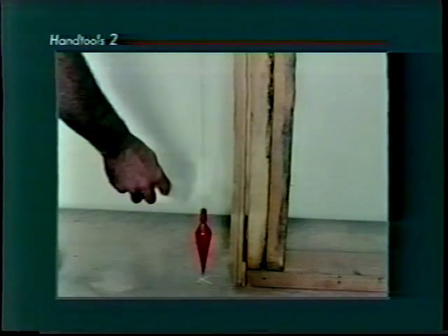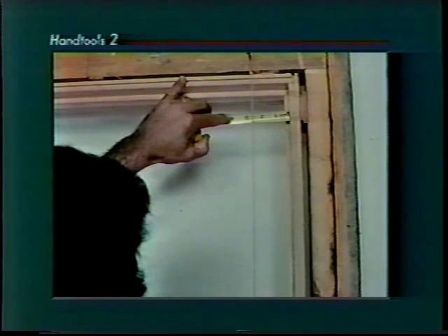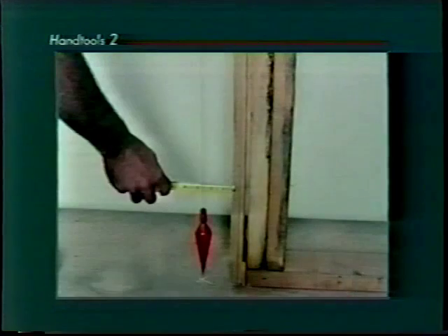Use the second method when the lower point is known. Locate the point below with the plumb bob and extend the string to the point overhead. Once the bob is motionless, mark the string point above and the line is then plumb. After you make the mark above, secure the string to a nail at that point. Measure the distance from the string to the vertical object at the top and then near the bottom to check for plumb.